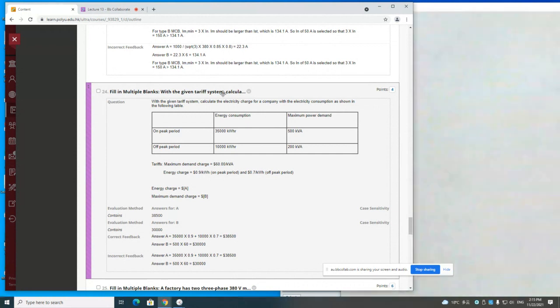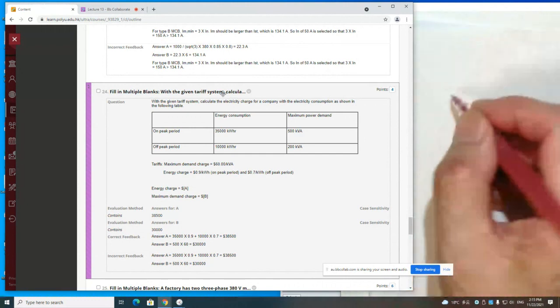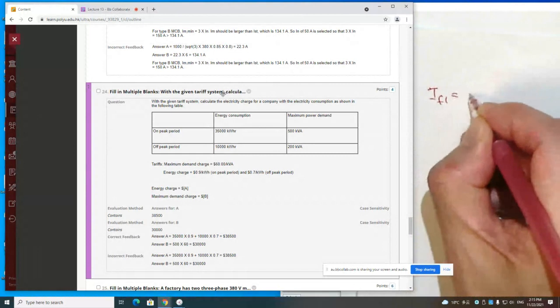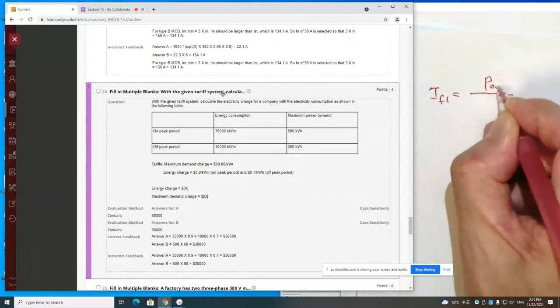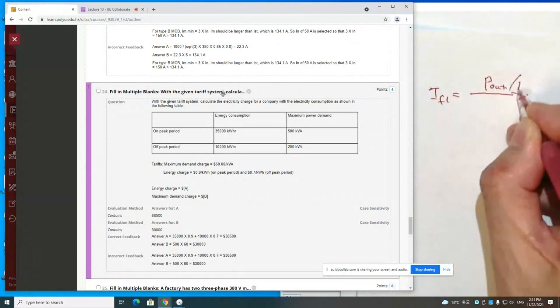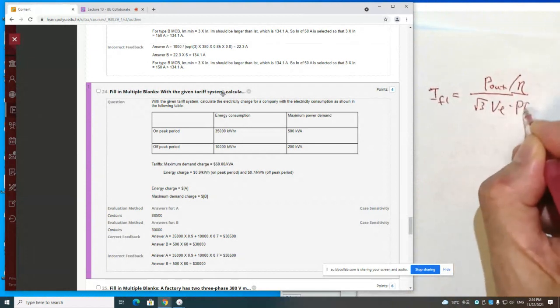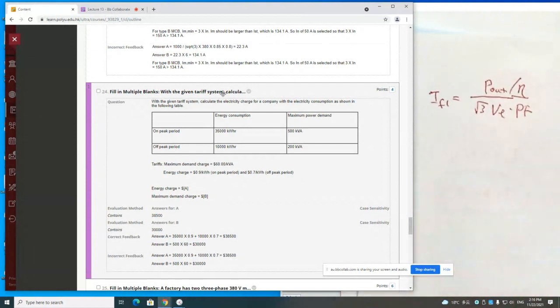Let's say full load current equals the output power of the motor divided by efficiency, root 3, line voltage and the power factor. Such a formula will not be provided, you are supposed to know it very well. But the formula for the IDMT relay will be provided.